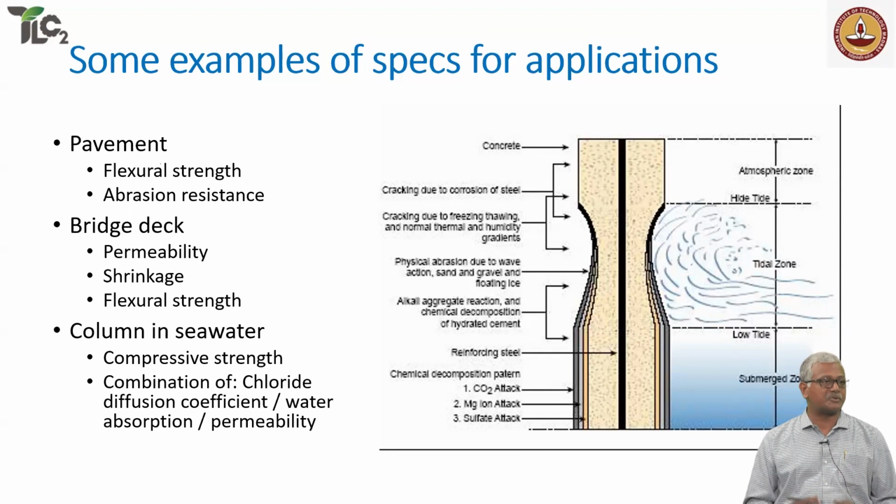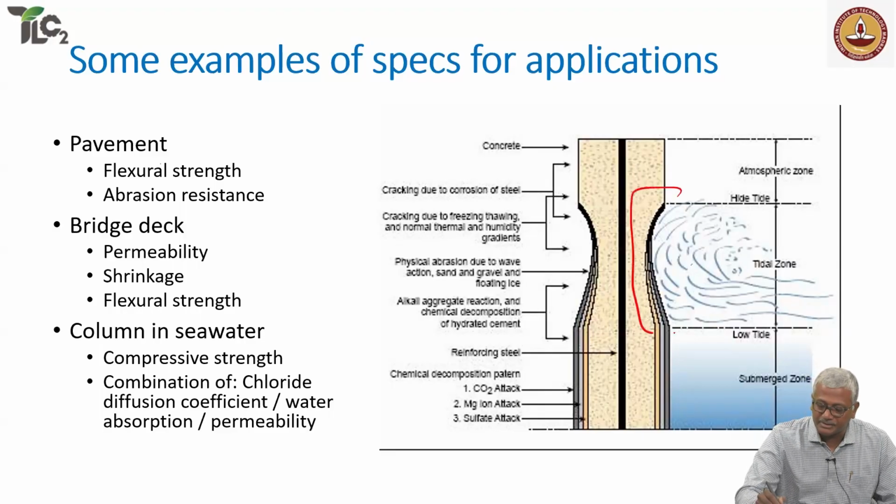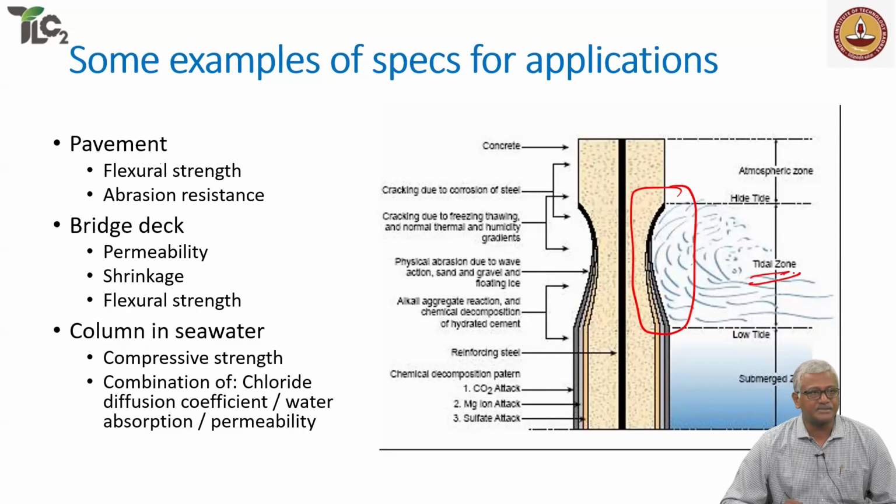These can be additional specifications that you can give for the concrete columns in seawater. The most critical zone to define in concrete columns is the zone which is affected by the tide. That's the most critical zone. That's where you need to define your extreme condition for seawater.